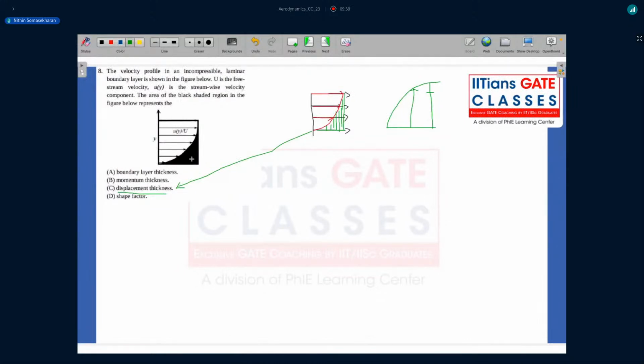Your momentum thickness does not only take into consideration this shaded region, it also takes into consideration the momentum that is being carried. The shaded region does not really represent the momentum; it only represents how much of a flow rate deficit is present. The mass flow rate deficit, not the momentum flow rate. And displacement thickness, as we mentioned, is what the shaded region represents. And shape factor is nothing but the ratio of displacement thickness to the momentum thickness. So that's an entirely different ratio that typically we calculate for certain shapes. Just to compare